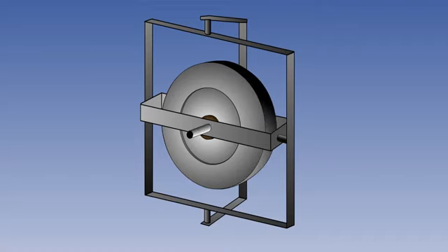Make a note, however, that by convention the degrees of freedom of a gyroscope do not include its own spin axis, and this is the reason why we say that 1 degree of freedom is provided by a single or inner gimbal, and 2 degrees of freedom are provided by an inner and outer 2 gimbal system.